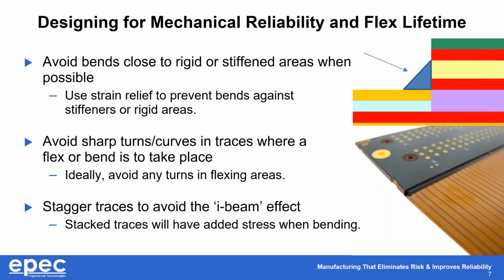From there, it actually does start getting into the design aspects of the circuitry. You're going to avoid sharp turns and curves in traces, especially where a flex or a bend is going to take place. Any areas where the bend is going to occur, just have absolutely no turns and curves if possible, or make them extremely gradual, such that the bend does not end up causing any issues.